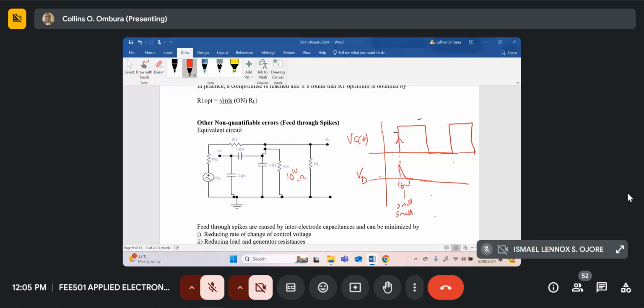Now next, when the FET is on, and we put a negative going pulse at the input to switch it off, it means during this point, the drain resistance is changing from 25 ohms to 10 to the power 10 ohms.